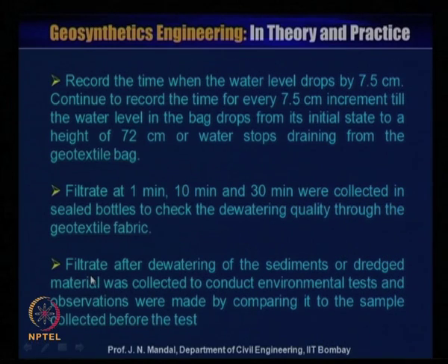Now, record the time when the water level dropped by 7.5 centimeter, and continue to record the time for every 7.5 centimeter increment till the water level in the bag drops from its initial state to a height of 72 centimeter, or water stops draining from the geotextile bag.